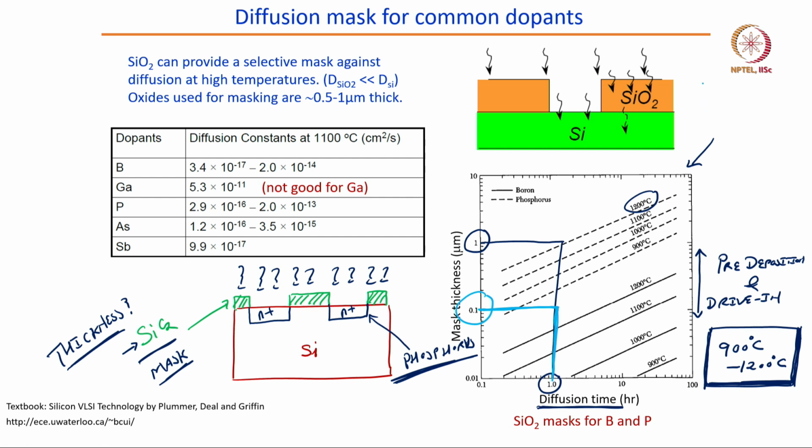All of you should understand 1 micrometer is equal to 1000 nanometer. So, 0.1 micrometer would be how much, right. So, based on that you can calculate how much is the thickness that you require for silicon dioxide, so to be used as a dopant masking layer for the dopant. Alright, I hope you understand. Now, let us go to the next one.